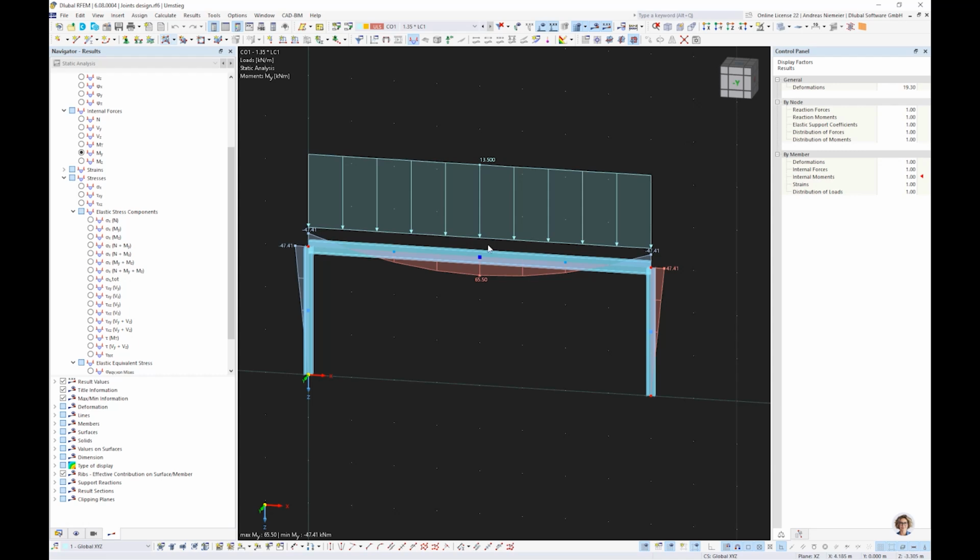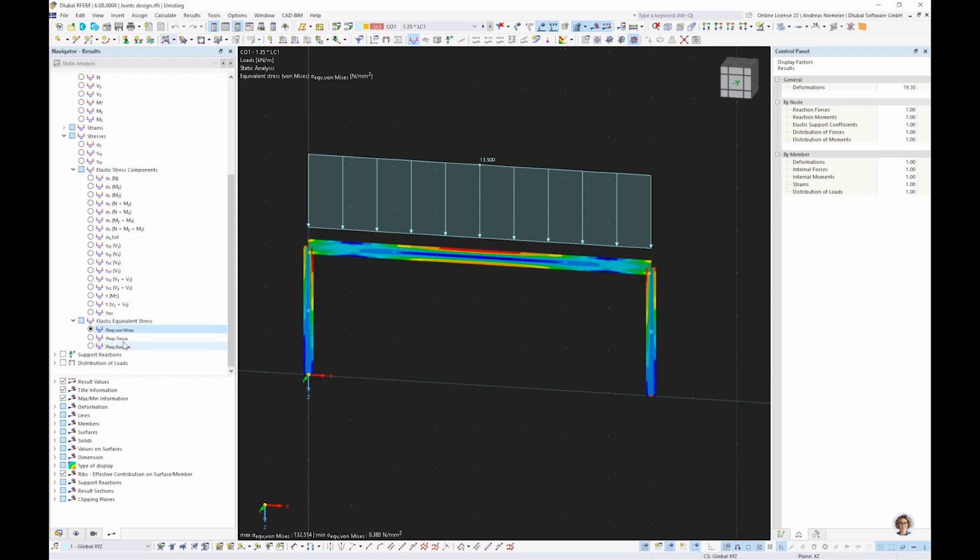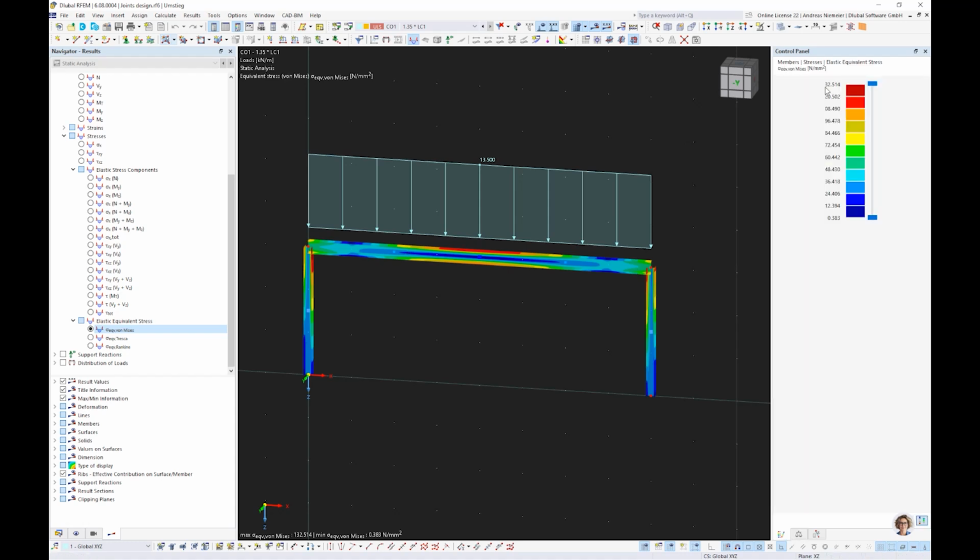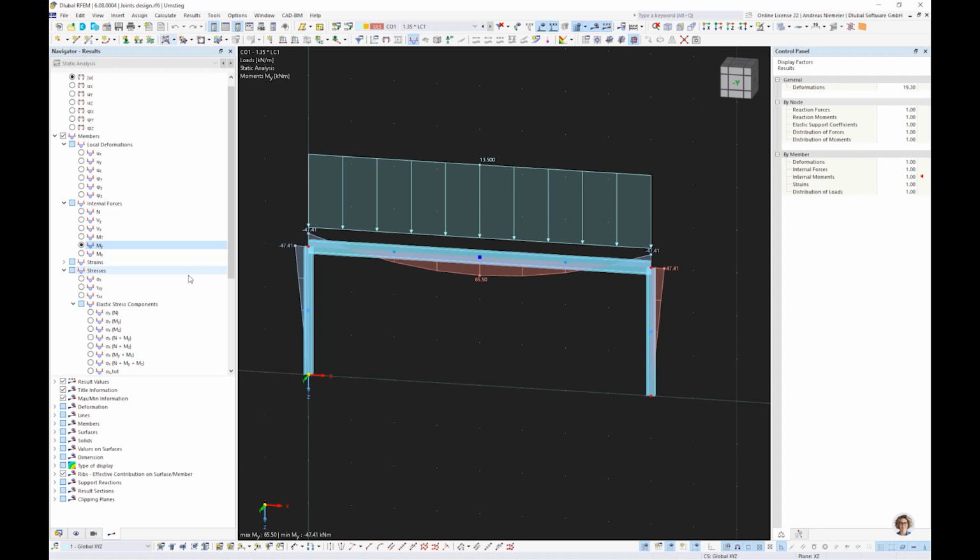But what are the genes of this model? Yeah, we have beams, we have now here stresses. Let's take a look at Mises stress. Maybe about 32 Newton per square millimeter on the beams. You see also here 0 point, and here again the restrainment on the column. Yeah. So far, let's say everything clear. And what is also interesting, we have here in the mid 65, here 47. But we don't know how the force is transferred from this girder to the beam.